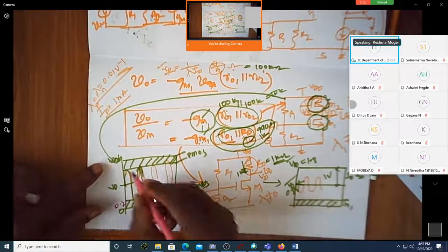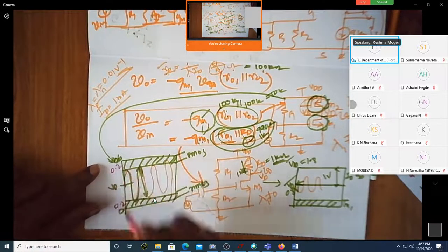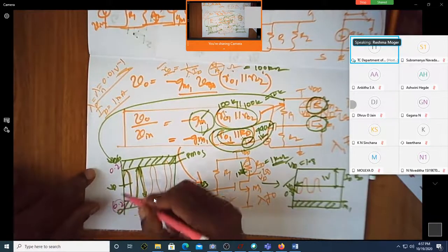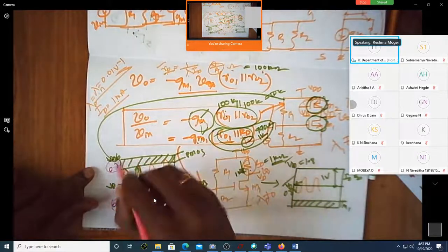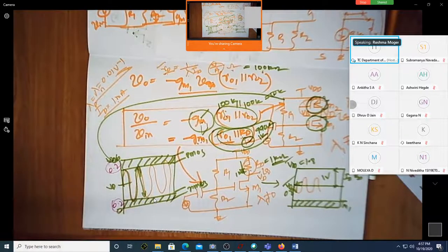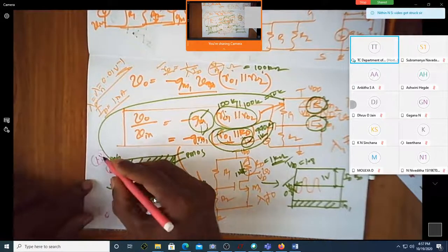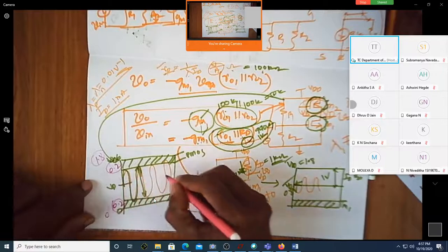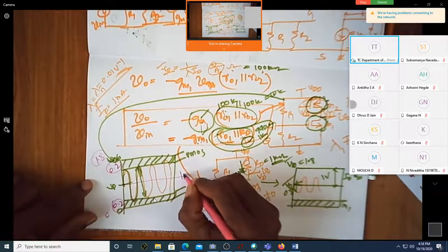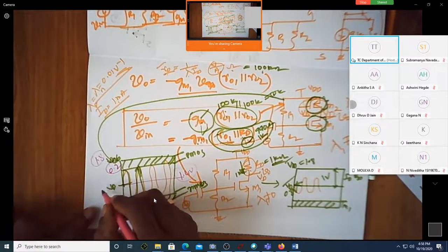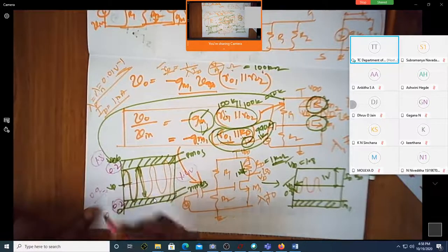Yes, sir. Over here, is it also 0.2? On the same lines, suppose the overdrive voltage is 0.2 here, is the overdrive voltage again 0.2 on the other side also? Yes, sir. Now you can see out of 0 to 1.8 volt, 0.2 is left out on each side. Do you have a peak to peak of 1.4 volt left for the swing if you are keeping this at 0.9?